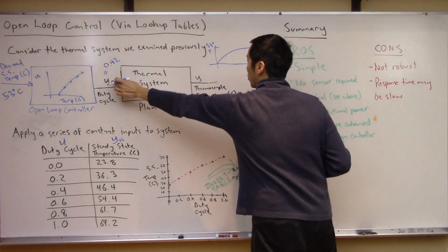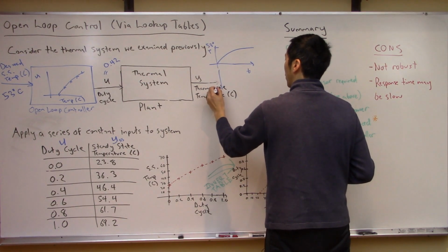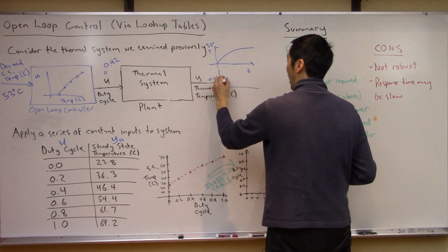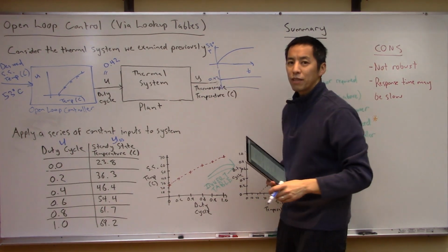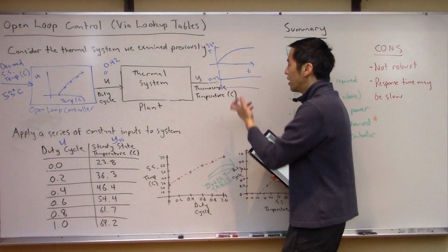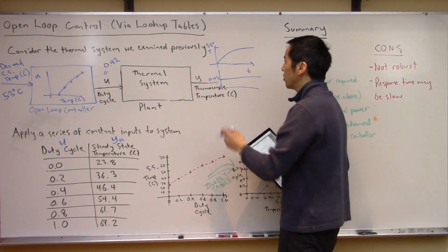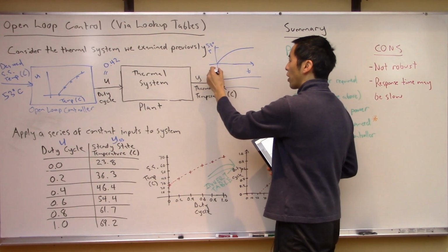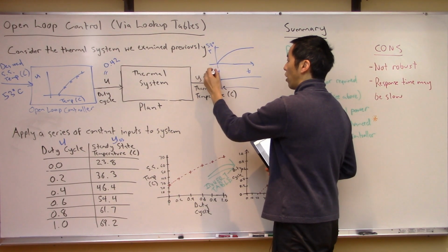because what this control signal over here is doing, if we were to plot this, it's just sitting here at 0.42. It's just flat, because you're basically looking up the steady state value. Well, this is kind of dumb, because you know you're way too cold here. So initially, you should be cranking this thing up to 100%.